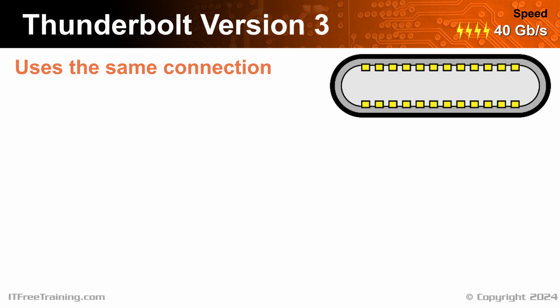Although this video is about USB, I will also need to have a look at Thunderbolt. For version 3 of Thunderbolt, there are two different standards, but that will change. More on that later. Thunderbolt 3 also utilizes a Type-C connector. Although the Type-C connector is often considered to be a USB connector, this is not true. The truth is that the connector can be used with any protocol. Since it uses the same connector, it also uses the same cable. But of course, there's a catch.